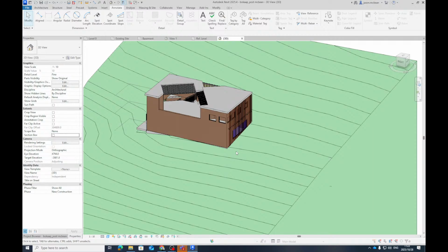Yeah, because we need a lot of detail for our construction. But remember, you're only showing one section and you're drafting what you think you should see there. This is giving you an outline of what's happening there. Then you draft the nitty gritty. Don't try and model everything. You'll see that the stairs won't connect correctly, so you have to draft over that to make it look correct. Welcome to construction drawings. It's very different to designing and modeling stuff in detail.